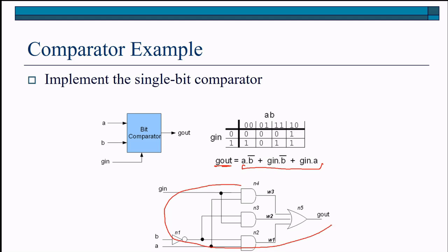And we can represent our Boolean equation using the basic gates shown here. So if we take our first term, A ANDed with B bar, here's our A term, here's B, we have not B at this point, so this is B bar. ANDing those two will give us this product term.